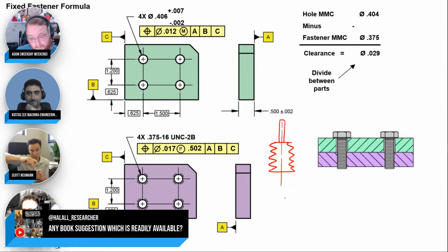But position on threaded holes is hard to measure. Are there any best practices for working with position on threads? Yeah, you probably use thread gauges. So thread gauges are like little things that you can put in there, and then they have a little stalk or diameter that sticks up, and that would be ground on the center of the pitch. And so then you can thread those into the hole, and now you've got this really nice precision diameter you can touch off of.